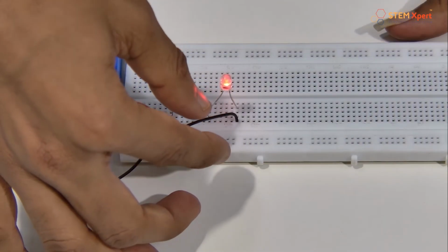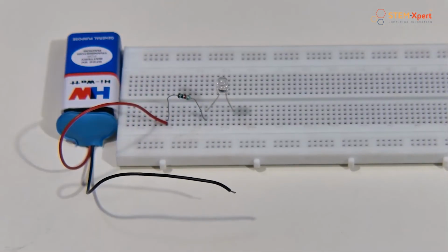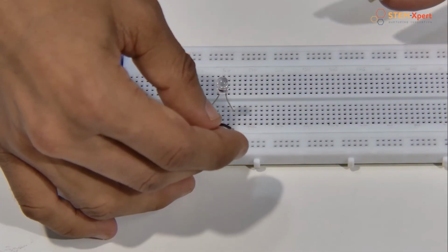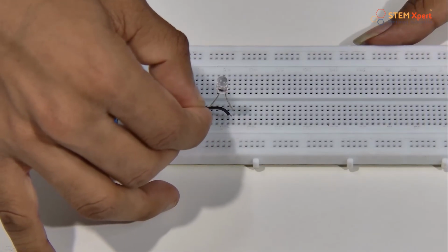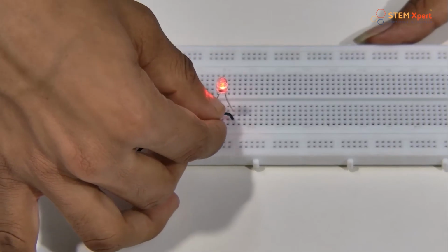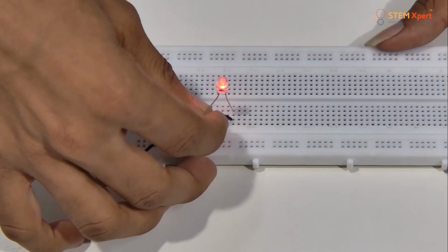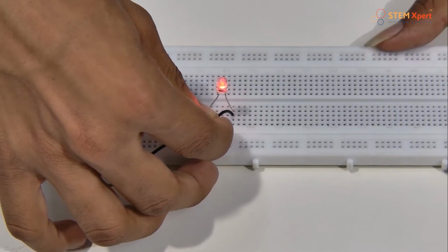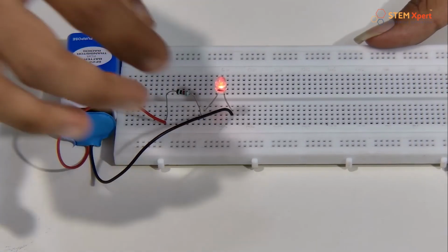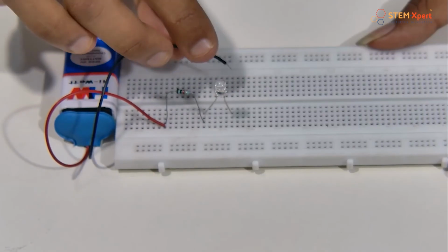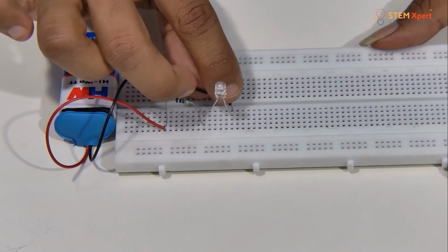So if I apply the negative point to any other point of that negative section of the LED, it will also work, because we already know that in the B part the connection goes vertically. That means if I apply the negative voltage of the battery here, it also works. Am I right? Yes. So what about connecting another point? Then I connect another point. See, our LED also turns on, right? Yes. So the last point here, if we connect it along with this point, it will definitely work.